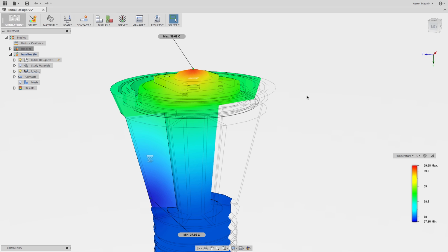So I mean, we can keep going with this. We can add 15 more fins. We can add 100 fins. Whatever we can fit in there. But we're constantly balancing the cost to the benefit, right? We don't want to make this out of an expensive material due to its highly conductive nature, or actually I've heard that some of these LED lights are starting to use active cooling mechanisms, so like fans and stuff.